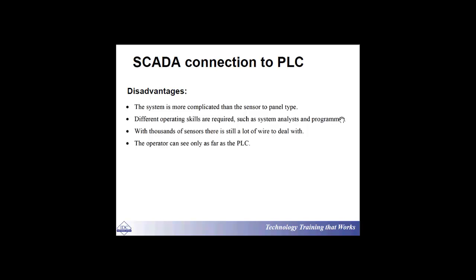So who's going to make the decision? Who's going to make the connections? The microcontroller. By means of what? By means of 61850. This is what I want to achieve. So that 61850 should be a solution maker in terms of many different things: the communication protocol, terminations, wiring, control logic, interlocking. Everything should be included in that 61850.